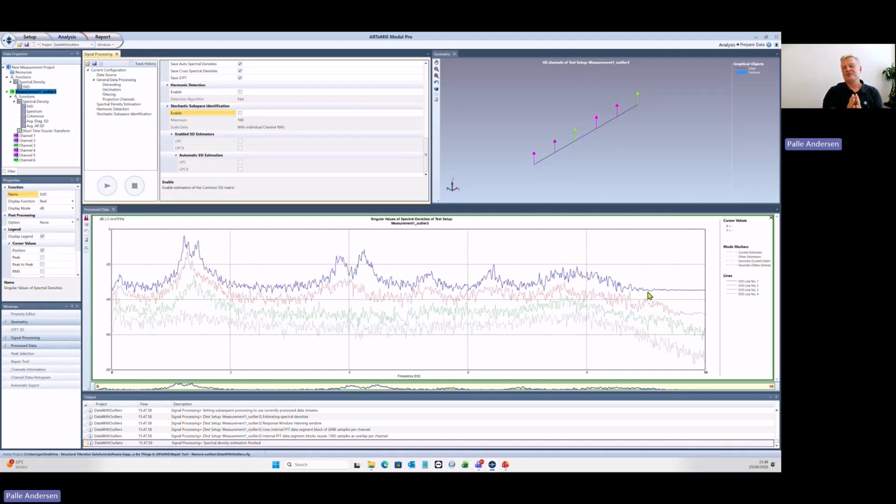And if you have something that is really sharp in time domain, it's really flat in frequency domain. And that means every time you have a spike, you get more and more flat noise added to your spectrum. So that's why it's a good idea to get rid of it, because it can help on the noise in your spectra. So let's try to see.